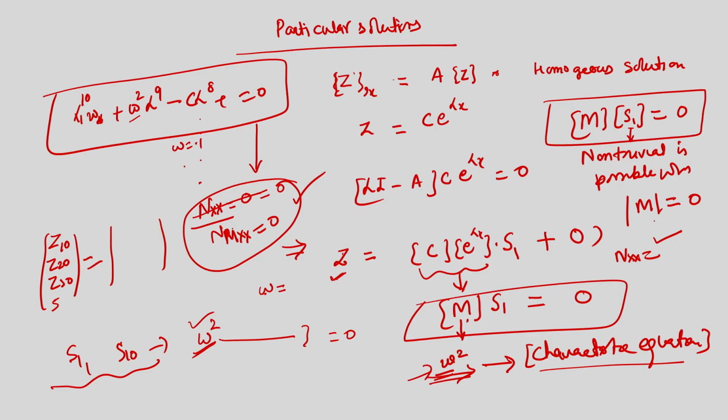but in the present displacement based formulation, Nxx, Mxx are not our variables. So, using the constitutive relations they are satisfied. From an accuracy point of view, in general there is no difference, only a difference may come up near the support at the very edge. If you plot the circumferential variation at a very clamped edge or at a very free edge, then some boundary effect may appear. So, to accurately predict that behavior, the mixed formulation is mostly preferred.